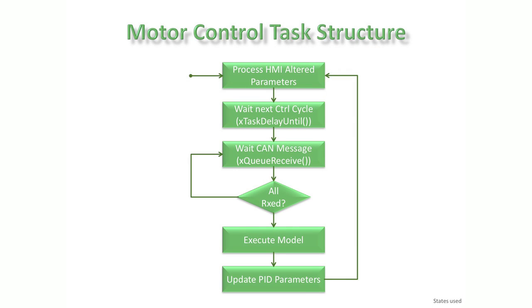So it then has to wait until the answers come back. So here's another FreeRTOS function, xQueueReceive. Again, X is the return type, Q is because it's defined in Q.C, and receive because you're receiving data. And this is a blocking FreeRTOS call. Now, by blocking, I don't mean that it's spinning on something and not returning. When it's blocked, it's not executing. That means other tasks in the system can execute.